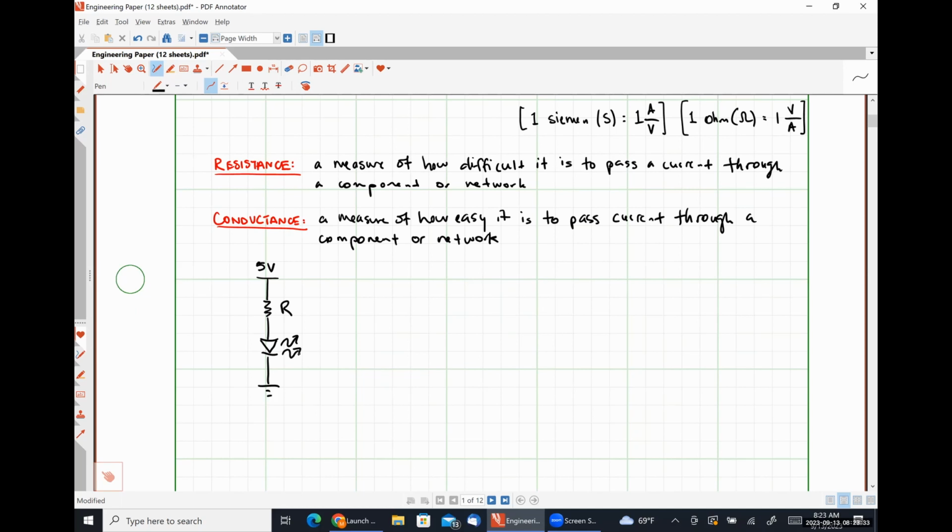So the reason why that's important is because we have this pesky thing called the passive sign convention that we talked about during our last class meeting that we need to obey, okay? So if I have a resistor R like so, and I define the voltage drop across my resistor with positive polarity on the left, which terminal has the positive polarity isn't particularly important, and my current I sub R is flowing into the positive polarity terminal, then Ohm's law tells us that V sub R will be equal to I sub R times R, right?